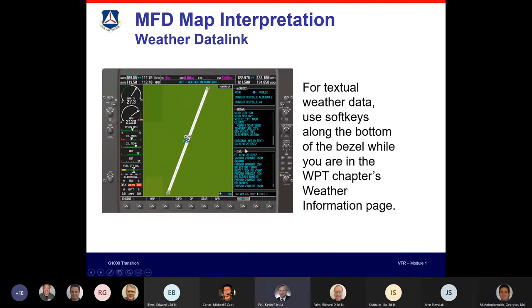What does it depend on at this point? The G1000 that we have worked great with XM, but since ADSB came, XM is an unnecessary expense, so that subscription has lapsed. But the systems have not since been configured to get their weather from ADSB, which is possible. Maybe it's a firmware upgrade, I don't know, or maybe it's just a configuration, but it needs to be done by a Garmin dealer. I don't think it's available to the user, at least as far as I know.